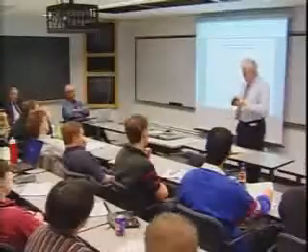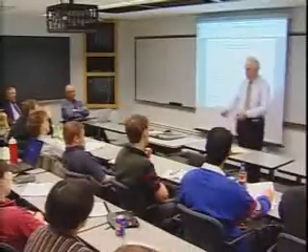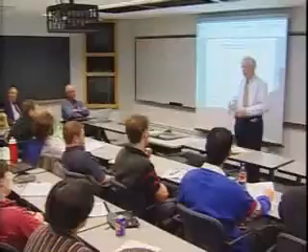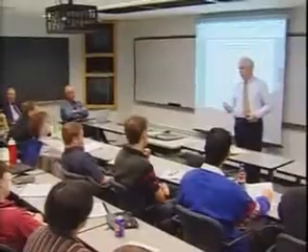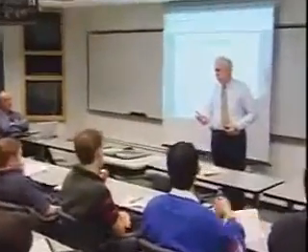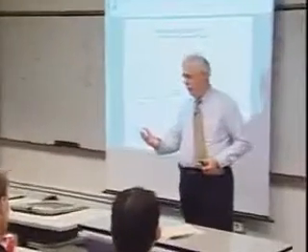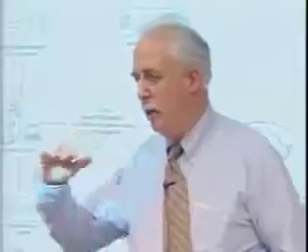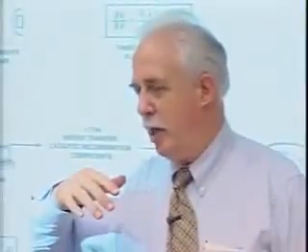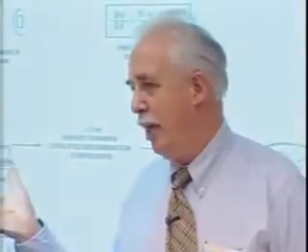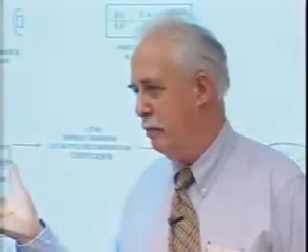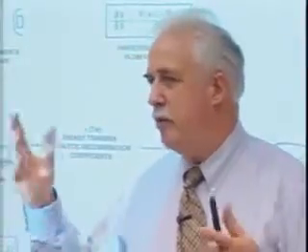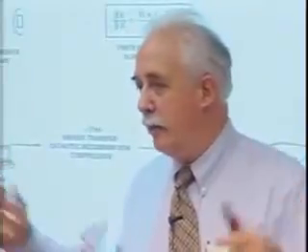The structures guys like to make things nice and flat or cylindrical, and the flow is continuous radius of curvature type phenomena. And that difference is very, very important, particularly for boundary layer transition. So we did fair the geometry to keep the boundary layer transition essentially 2 orders of magnitude lower than it might have been. But overall, I'd say predominantly is aerodynamics, and we tried to calculate the heating to the configuration that we had.